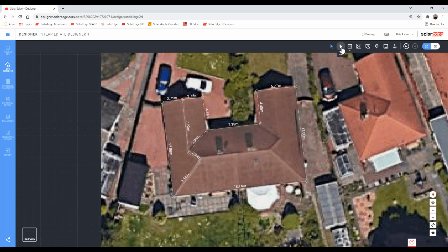Simply join the dots. I'm going to draw the ridge line across. Again, you can see a nice angle here as I come across, and I'm looking for the software to tell me where to finish the line, which is there. Draw function again. Again, I'm going to carve at the correct angle.